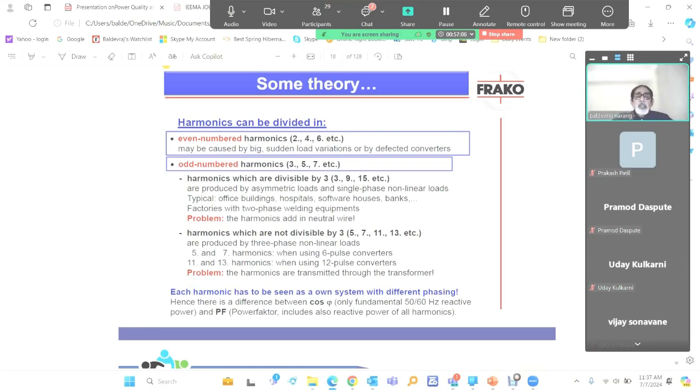So fifth and seventh harmonics are again positive sequence and negative sequence harmonics. So all harmonics create overheating, whether it is third, fifth, or seventh. And some of the common problems are there, which we'll discuss in the next slides. But third, as I told, more particularly from single phase loads, there we have to strengthen the neutral, besides other measures like harmonic mitigation through filters.